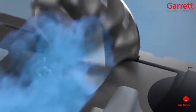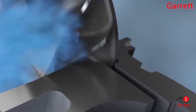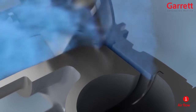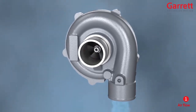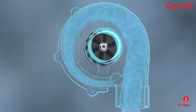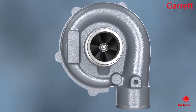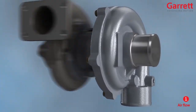As the air passes out from the compressor wheel exducer or outlet blades, it passes through an area between the compressor housing and the backplate called the diffuser, which increases in area and allows the high-speed air to expand and slow down, and this creates a high-pressure zone. The air exits the diffuser and continues its journey through the volute, which is again shaped like a snail shell with an increasing section towards the compressor outlet. This continues to allow the air to expand and slow down, ensuring that when the air reaches the compressor outlet, it has reached maximum pressure and density.